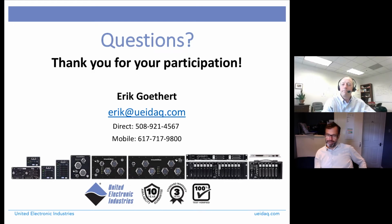Yeah, I could take that one. So, it really depends on what type of failure occurs in the grandmaster. If it was complete failure, then our system that would have been acting as a PTP slave would then realize a grandmaster is no longer on the network, and our system would go through what's called the best master clock algorithm. And our system as well could become the grandmaster on a network.